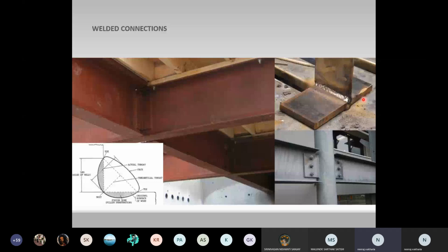But of course, we do have to design the welding conditions and the area which it is going to connect, then the material which is going to be used for welding, also how deep the weld is, because when we are welding these connections, the heat is about 3000 to 4000 Celsius. So at that level we don't want to puncture through, or reduce the thickness of material by melting too much of the metal.